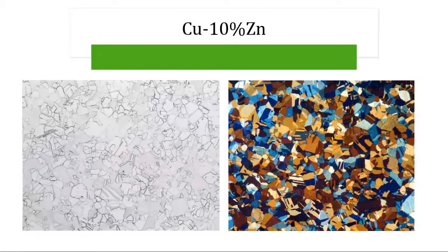The image on your left was etched with potassium dichromate, which is used for general microstructural characteristics, just to reveal the general microstructure. Looking at that microstructure, I see a decent sized grain here, and all of a sudden, oh man, that's a large grain, and wow, this must be a large grain here. The real microstructure hasn't been revealed.